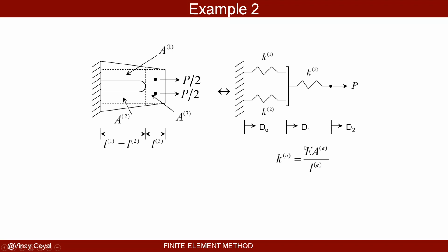So the modulus of the material times the cross-sectional area divided by L, where A here obviously is varying, so you have to be smart about what to choose for area. You could choose the average between here and here, for example. So maybe you can choose somewhere in between for that area, because you're idealizing, right? It's an approximation. That's what finite element is. It's an approximation. And you can make some simplified assumptions that you want to do.